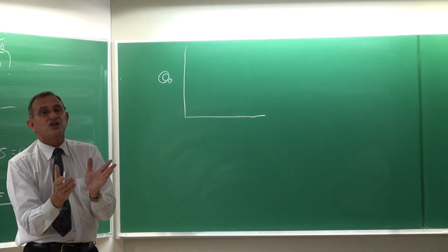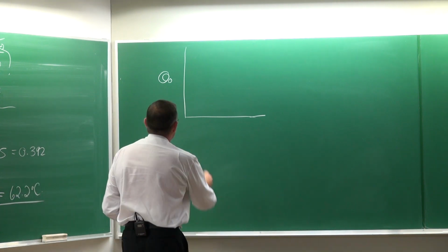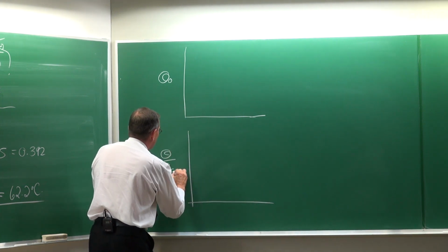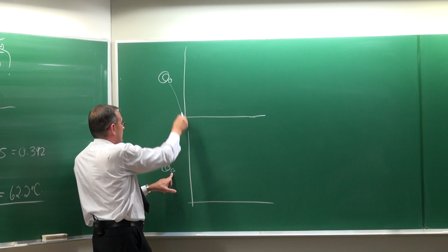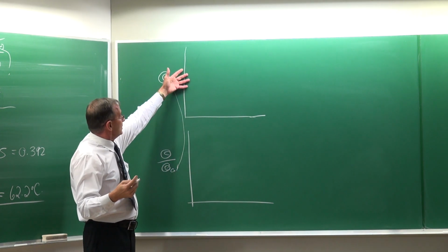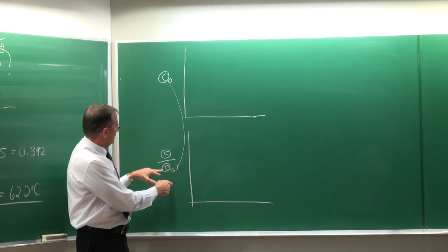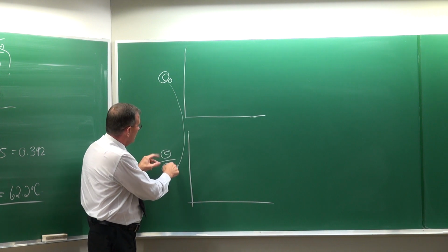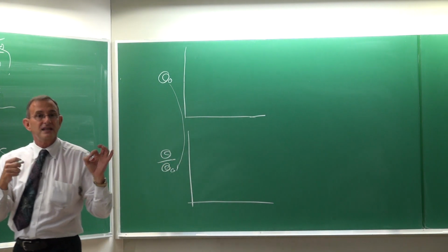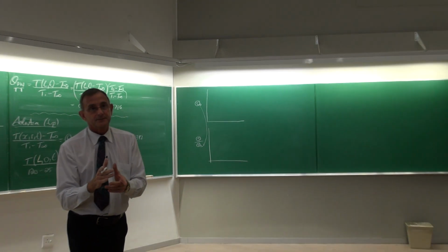In most cases, we as engineers are interested in the temperature at the center. The second one will give you the temperature anywhere else, after you've normally calculated that value. So from the Heisler chart's point of view, it is always best to get it at the center first, but then you need to have it as a ratio. What you're going to solve is a ratio of the temperature divided by theta 0. In the equations, it is not necessarily like that.